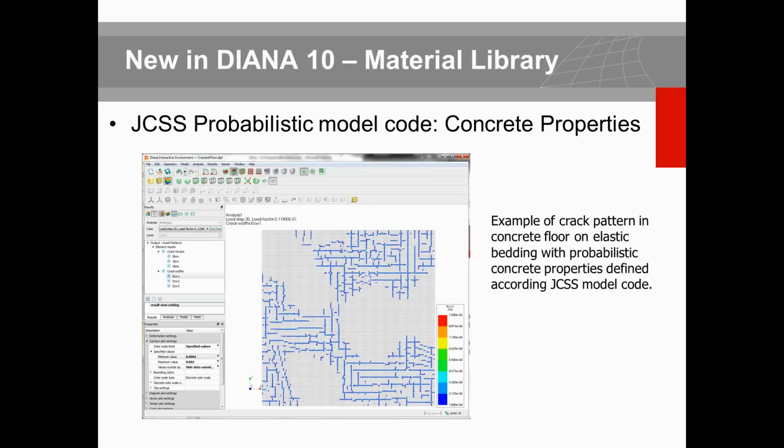Having those heterogeneities introduced into the model, if we have a slab like that which is subjected to shrinkage, you can see the type of cracks that are generated in the model. So it's not that the whole surface is all of a sudden subject to cracking. Based on this random field distribution, you can see one part is weaker, this part is weaker, and the other part is a little bit stronger. So the cracks happen in the weaker parts. This is basically the reality of the model that you want to consider to localize the failure in your model, by considering the realistic behavior of the material property distribution in your model.